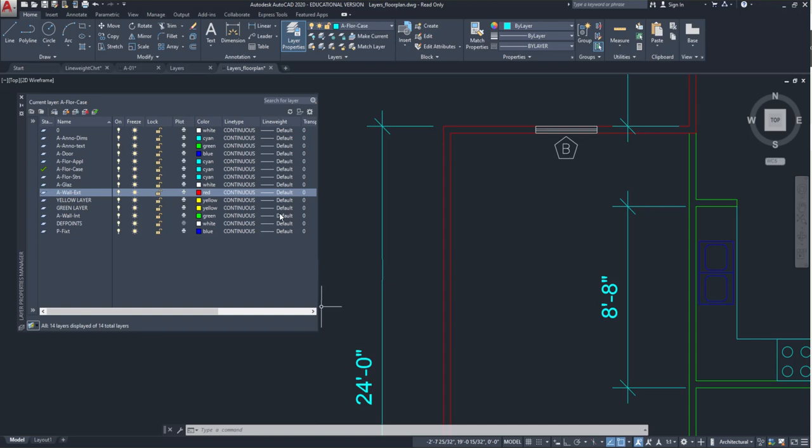Yes? Is there a reason why the depth points... Yes, so that's a good question. I'm glad you said that because I probably would have forgotten to talk about these other two special layers. Okay, so within our layer dialog box, you can create new layers, you can delete new layers. There are 2 layers in there by default that you just really for now don't want to use, okay? We have layer 0 up here and we have a def points layer, all right?